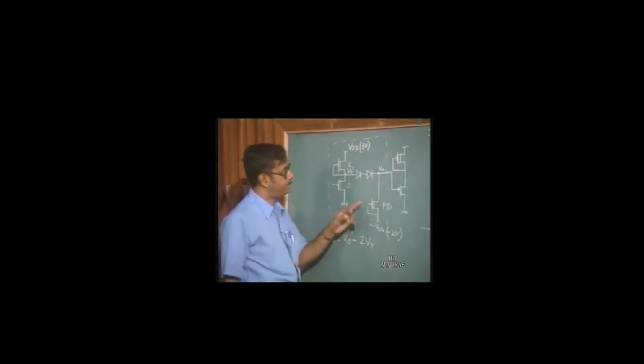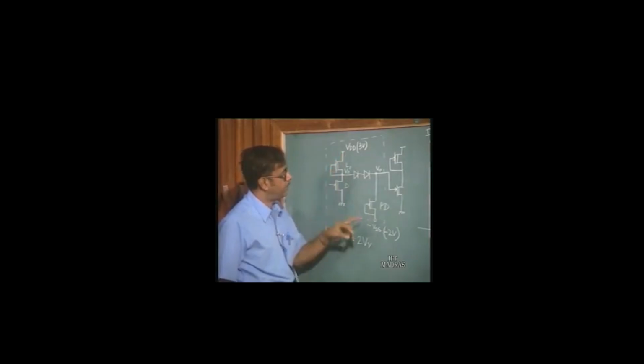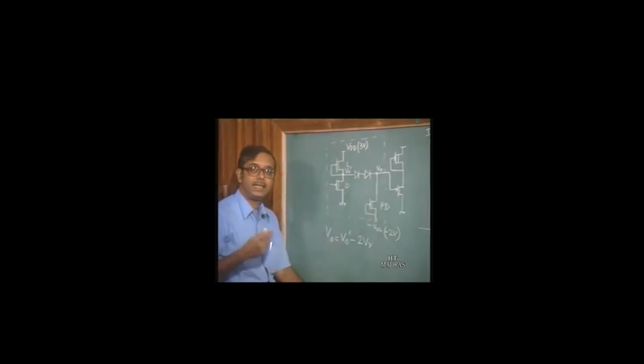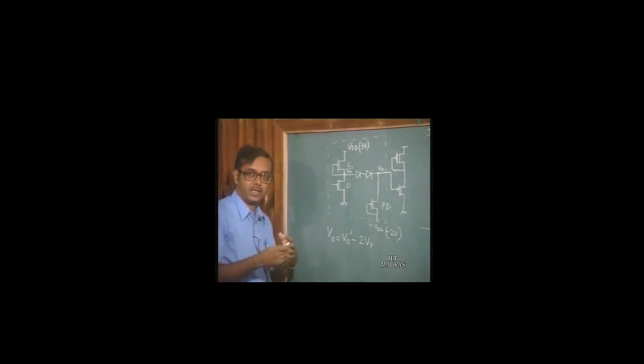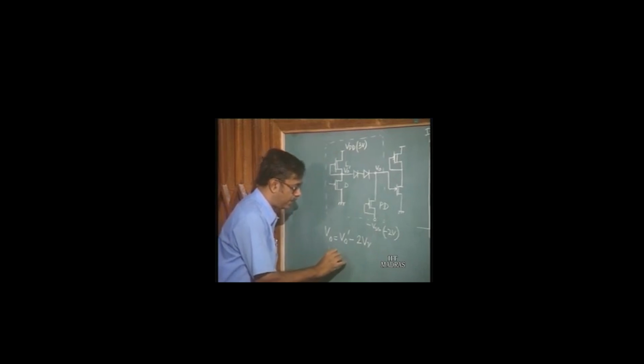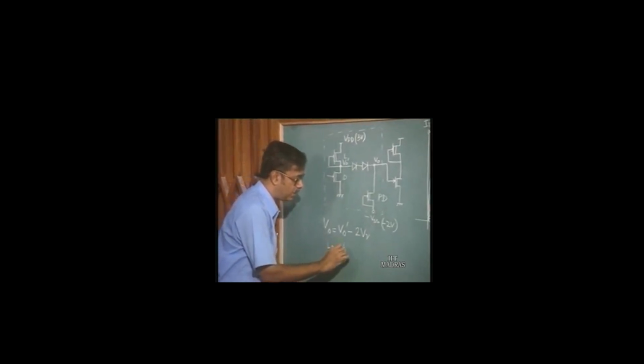Okay. So, you have VDD minus VSS. Now, as we have already said, the channel length of each transistor is always maintained at the minimum value. So, we have the driver transistor length equal to the length of the load transistor and equal to the length of the pull down transistor. But the width of the transistors will be adjusted.